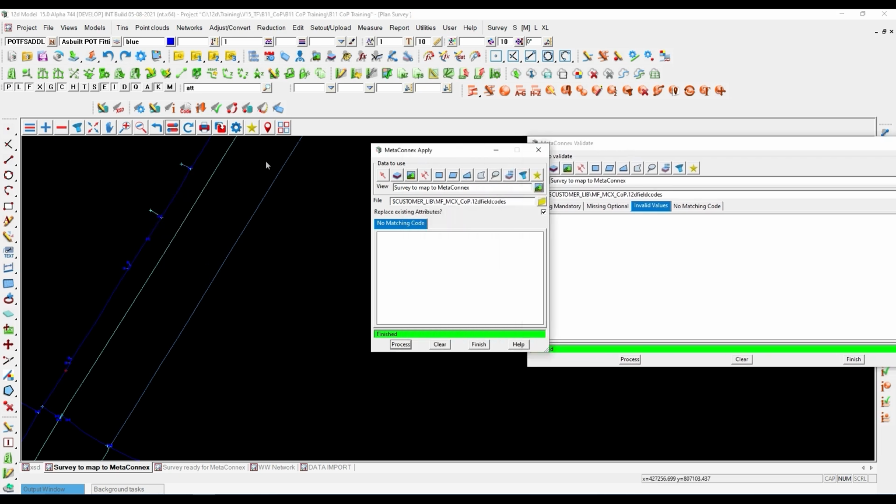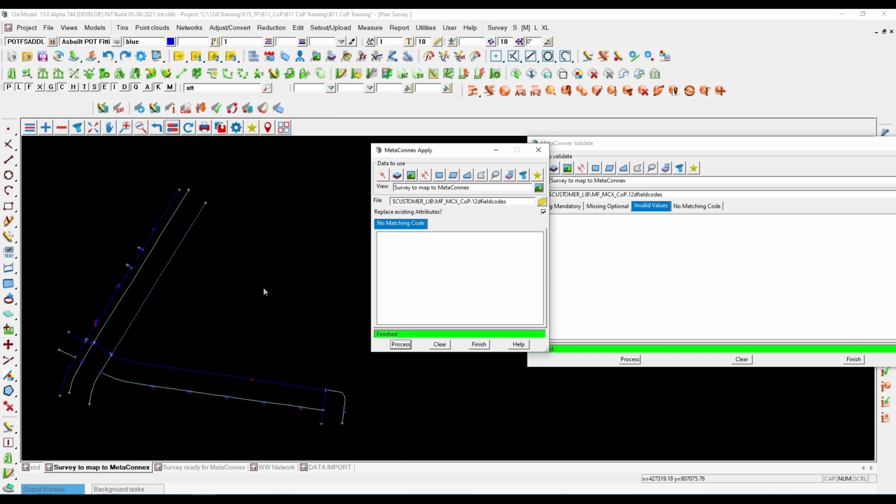So I've got a chain that actually creates the unique identifier for the water assets. If I apply that chain, it will go through and do a filter selection. And the filter selection will find every single one of the valves, the fire hydrants, and put a unique number starting at 1 and then progressing through, and the same for the pipes. So if I just run that now,